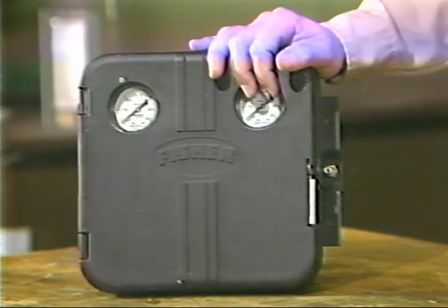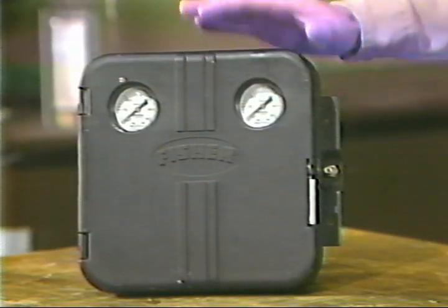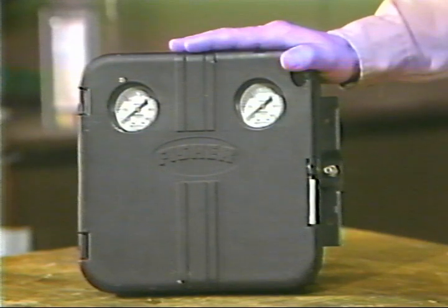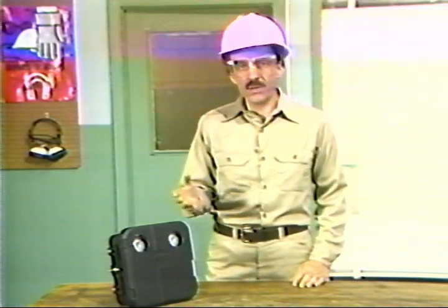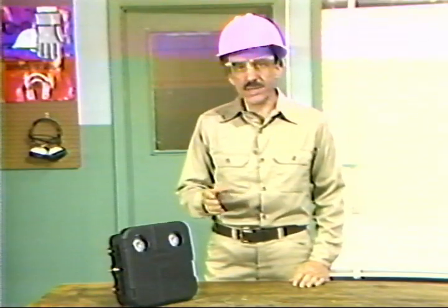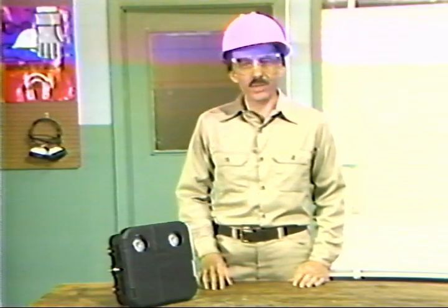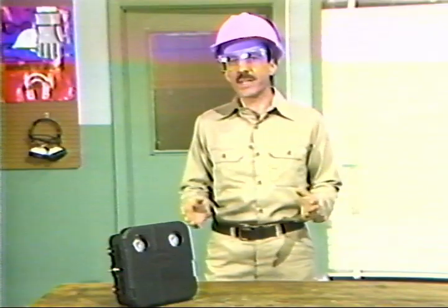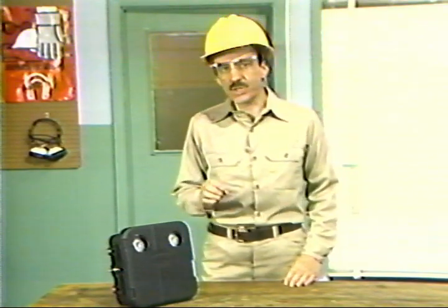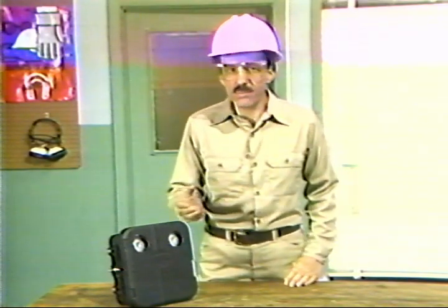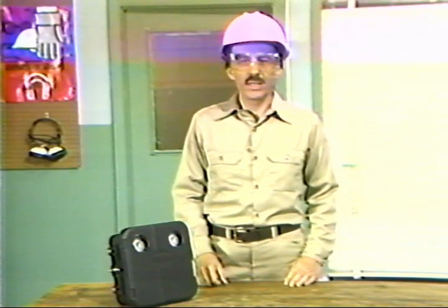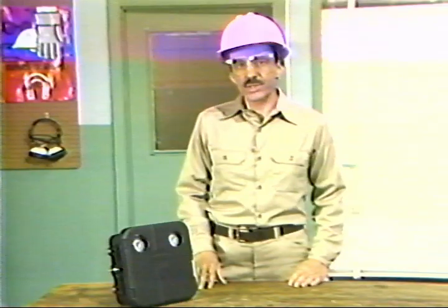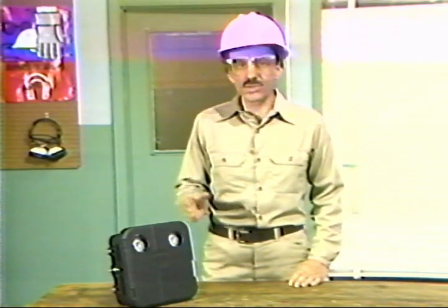A proportional plus reset, or reset controller, combines proportional control with reset control. The reset portion of the controller's output repeats the amount of proportional output for as long as the process variable deviates from set point. The addition of reset eliminates offset because the controller is designed to supply an increasing amount of output to counteract the deviation of the process variable. This increasing amount of controller output is based on repeating the controller's normal amount of proportional output.